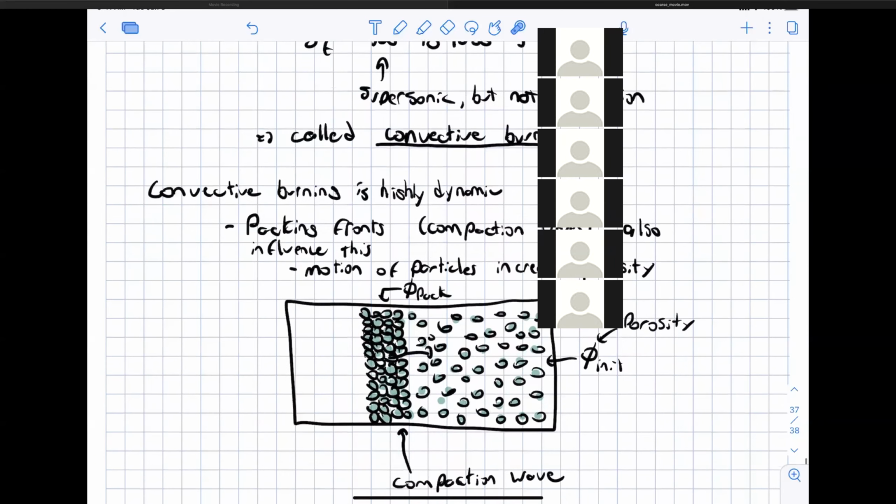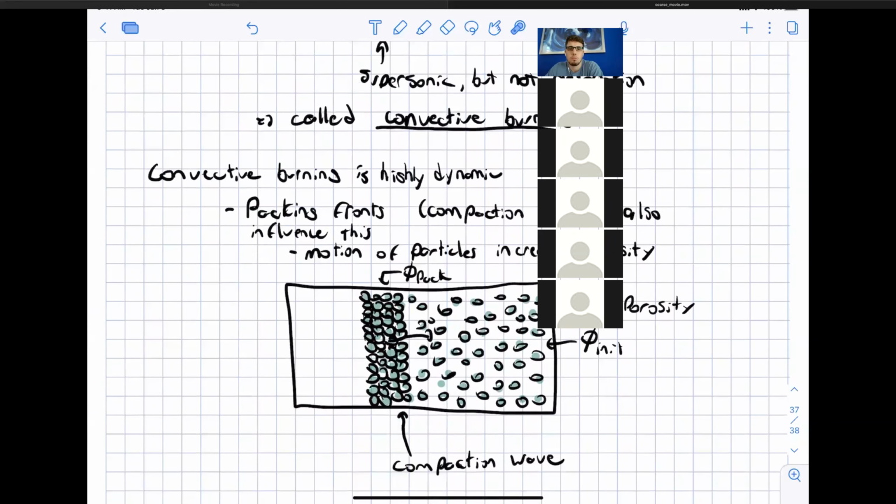It's also extremely dynamic. If you had a burning propellant and you wanted to model it, when we studied dynamic burning, it would definitely be in the truly unsteady burning regime, because the dP/dt would be extremely high. And the flow would be extremely fast. Everything about it would be sort of off the charts. And also the dynamics of motion of the propellant bed become important.